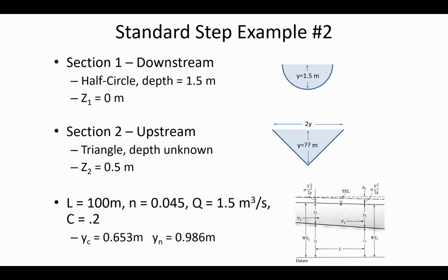And then when we do the wetted perimeter, we need to know the distance on the sides, using a squared plus b squared equals c squared. So this section length would be the square root of y squared plus y squared, and there's the section on the left and the section on the right to get the wetted perimeter.